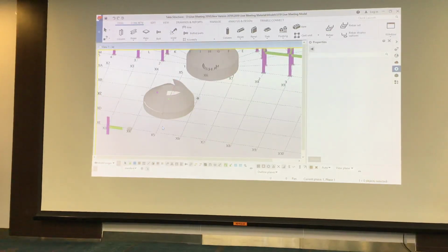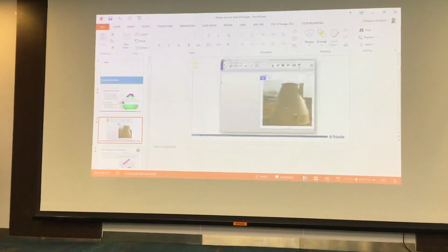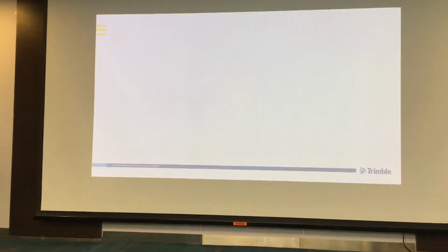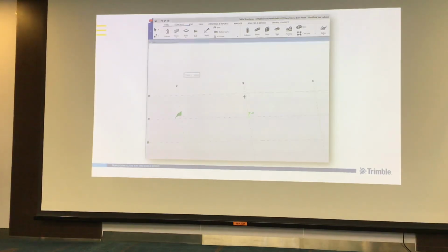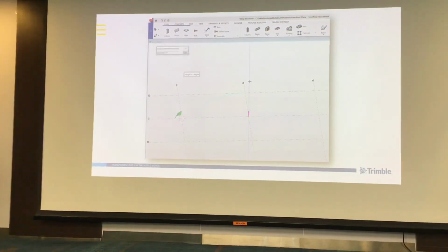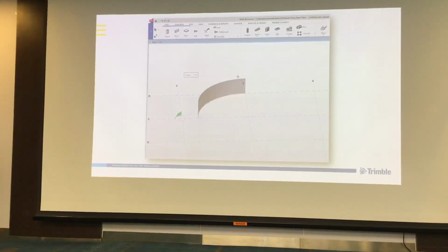So that was the addition of the bent plate. So to create this kind of object now is quite easy. You select the center point, you select the angle, you select the height, direction of height and what's the height, and then what's the kind of radius, and is it just straight or is it angular?